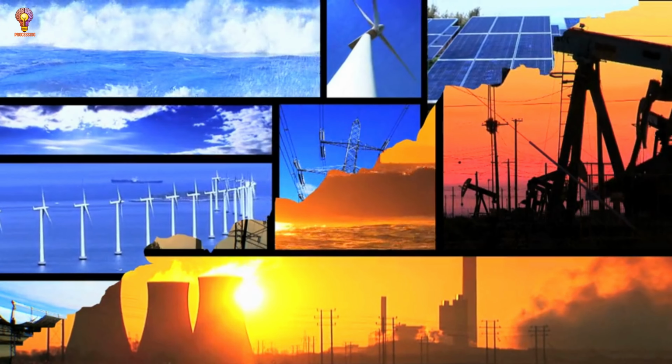Step-by-step process. Fuel combustion: coal, oil, or natural gas is burned in a boiler to generate heat. The heat converts water into steam at high pressure. Steam drives the turbine. The high-pressure steam flows through a steam turbine, causing it to spin. The turbine is connected to a generator, which produces electricity. Cooling and condensation: after passing through the turbine, the steam is cooled in a condenser using cooling water. The cooled steam turns back into water and is recycled into the boiler. Power transmission: the electricity produced is sent to a transformer, which increases the voltage for efficient long-distance transmission. It then travels through power lines to homes and industries.